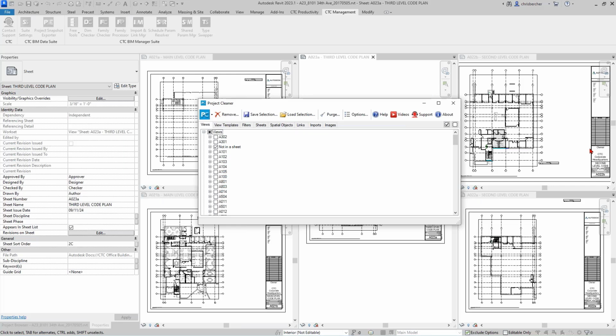Is there any way to recover a purged item if mistakenly removed? Great question. There's two ways to do that: close without saving and reopen it, or you'll just have to roll back the file if you're working on a work shared project. If you noticed it immediately, you could do either undo, which undoes everything, or close without saving. The app itself doesn't remember what you did in your last session. So it's not going to be able to go ahead and restore that for you.